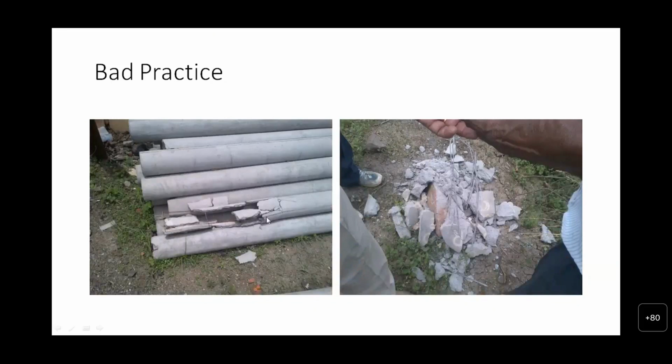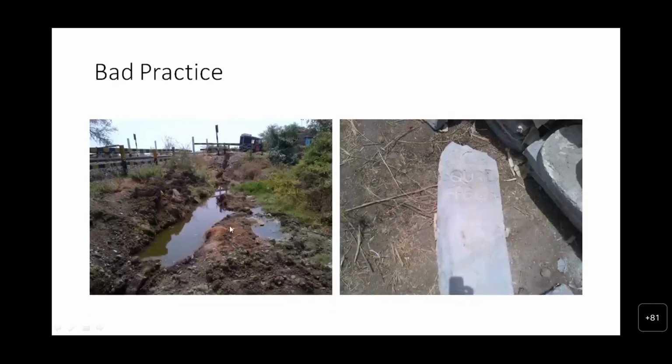So this is some of the bad practice. The quality of the RCC pipe is not good. One should measure and test before the utilization of the RCC pipe. A sample test has to be done. Similarly, this is a cable marker, which was also not of good quality.